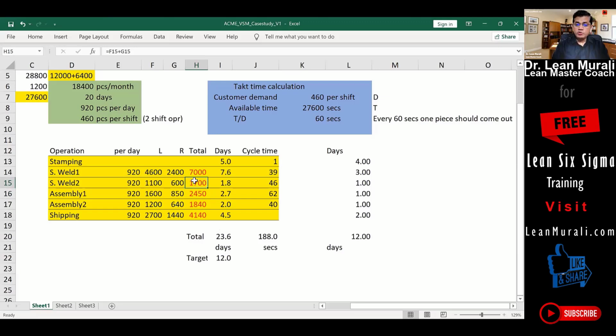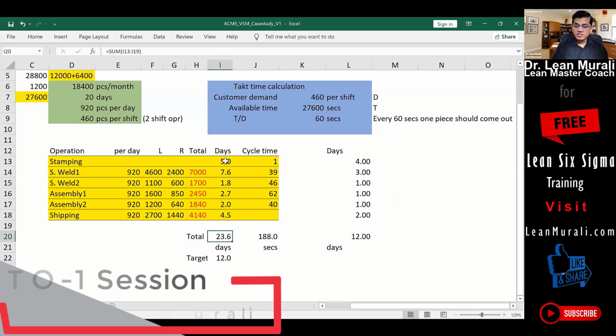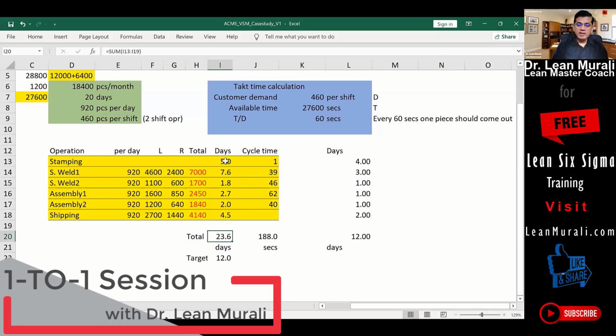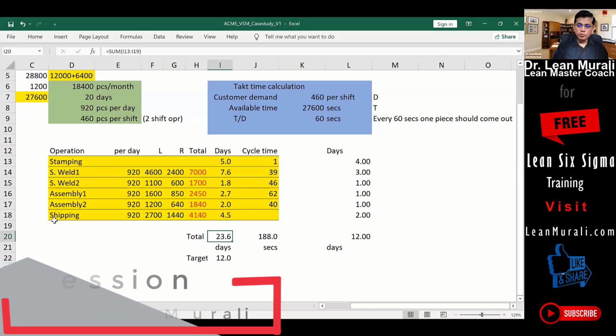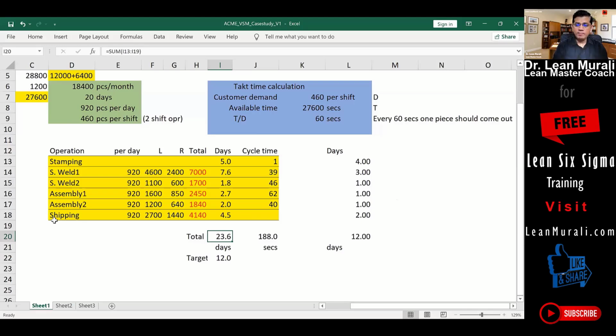So now this snapshot, the team has agreed that this is a representative inventory. What we have seen today is mostly the representative inventory. If it is not, we can see the past data and populate it here. But the point here is we need to see how many days of inventory there are. We see that it is 23.6 days of inventory. What does it mean? It means that any new bracket that I have to manufacture has to pass through, assuming the manufacturing happens first in, first out.